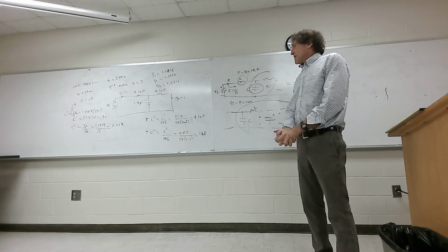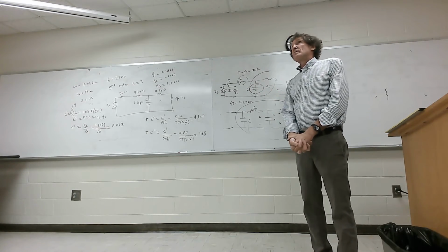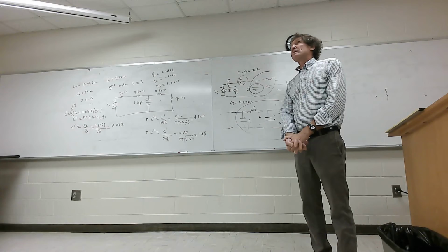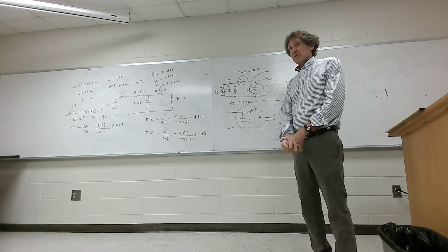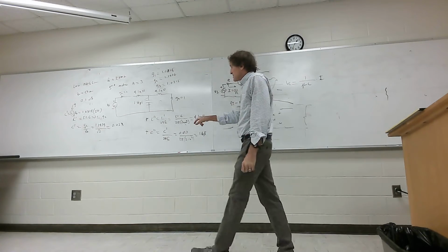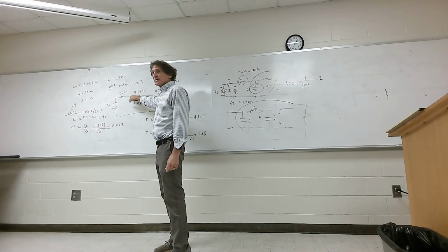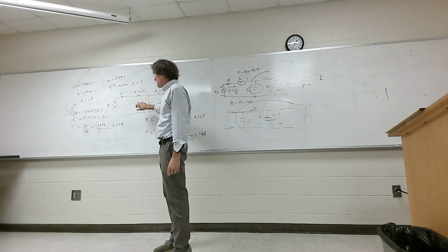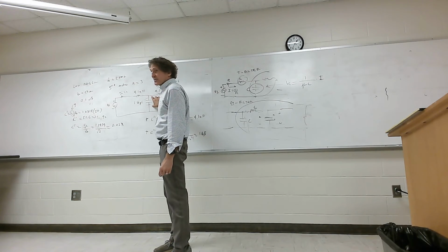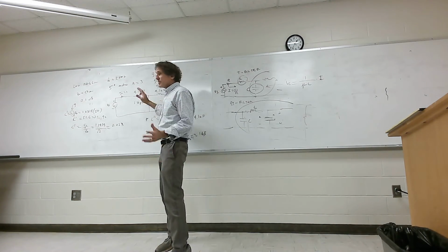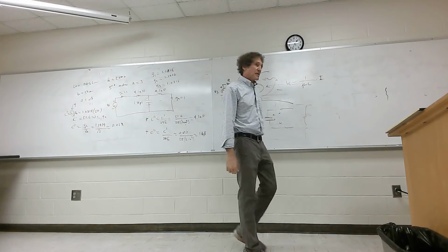The actual band stop and band pass will be the last thing we cover next time. The only difference is that instead of having a single element here, you're going to have a series inductor-capacitor here and a parallel inductor-capacitor here. And this is in the book. That's the only thing, because then the pass band will be there.